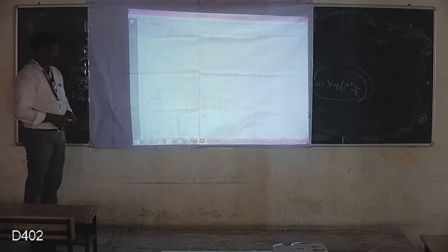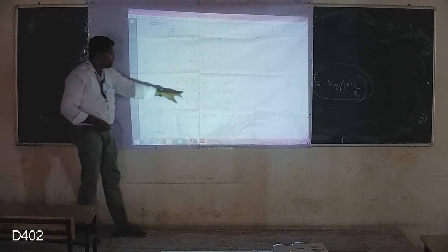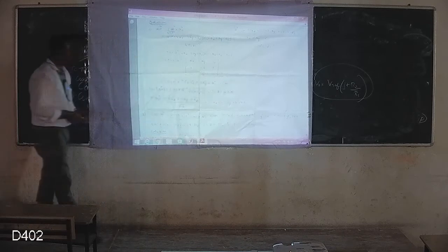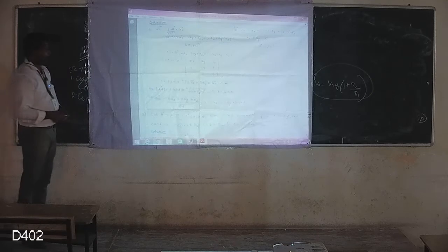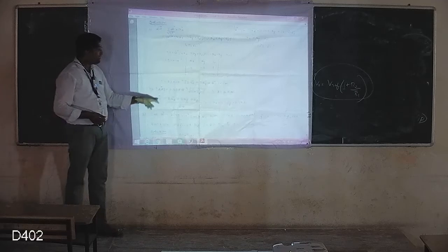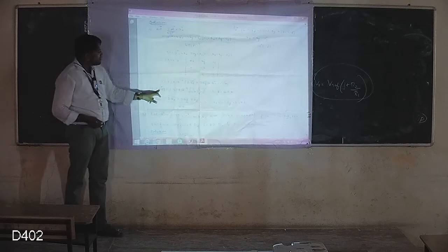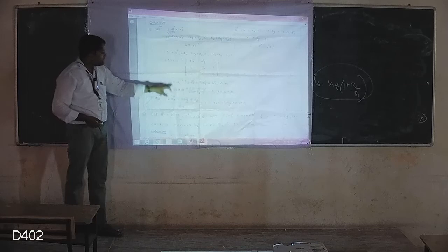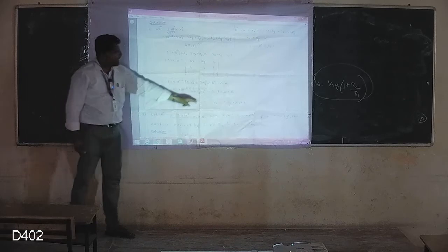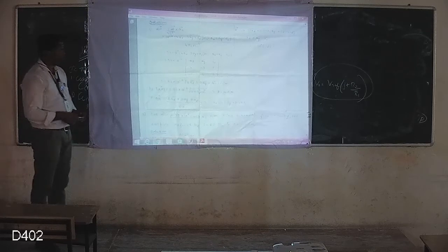That is the dH vector. To find the modulus, I take the magnitude. The common value is taken outside, and 2 square, 3 square, 1 square gives root 14, so the magnitude is 5.7 micro amp per meter. Now I have to find the unit vector. The unit vector for H is equal to dH divided by modulus of dH vector. Dividing this value by root 14, the common factor cancels, and expanding gives 0.5 aX plus 0.5 aY plus 0.27 aZ.